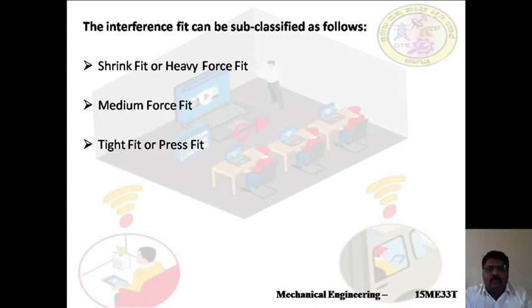And then the medium force fit. These fits have medium negative allowances and considerable pressure is required to assemble the hole and the shaft. It is used in car wheels, armatures of dynamos, etc. And the third one is tight fit or press fit. So one part can be assembled into the other with a hand hammer or by light pressure. A slight negative allowance exists between two mating parts. It gives a semi-permanent fit and it is used on a keyed pulley and shaft, rocker arm, etc. So these are the three sub-classifications of interference fit.